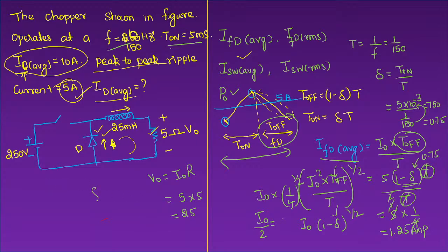So if you calculate the value of delta, this is a buck converter, right? So V naught equal to delta times of Vs, or we can say V naught by Vs. V naught value is how much? 25, whereas the value of input is 250. So I can cancel it. 0.1. Okay, there is some mismatching in the data. No, this value would be same, ma'am. You have to observe here. There may be, they haven't observed while giving the data.